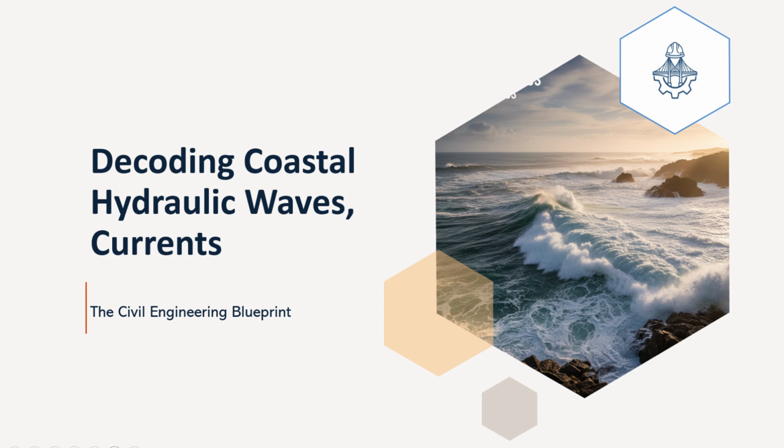It absolutely does matter. The surf similarity parameter, also known as the Iribarren number, is a useful dimensionless parameter that helps characterize the type of breaker we can expect. It relates the beach slope to the wave characteristics. It's often calculated using the deep water wave characteristics, where β is the beach slope angle and H0 and L0 are the deep water wave height and wavelength. The value of ξ tells us about the breaker type.